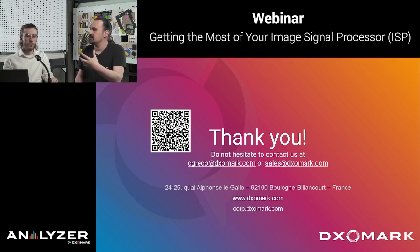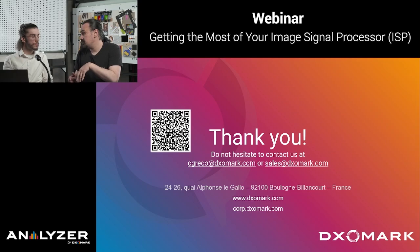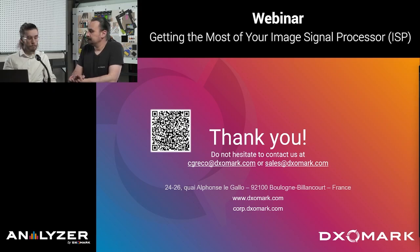I might want to boost the contrast a lot so I can easily detect shapes, for instance. My handling of sharpness versus noise might also be different, because maybe I don't need a very sharp image of the person, but I have to be able to detect it from the background when there's somebody dressed with dark clothes in a dark environment, and I don't want it to be completely covered with noise. So we are probably going through the same steps we did, but you're making your choices differently because your trade-offs are different, because the purpose of your image is different. Well, thank you for your question.